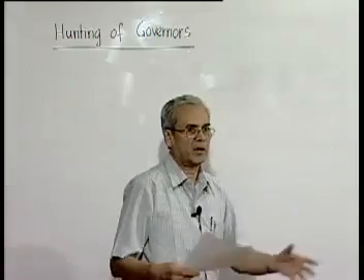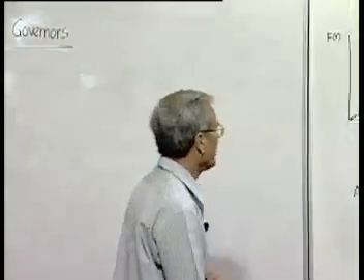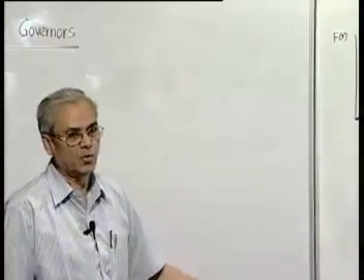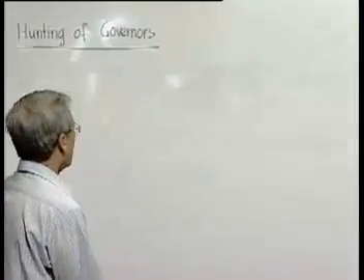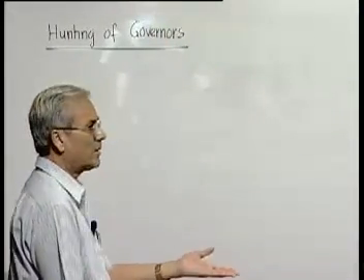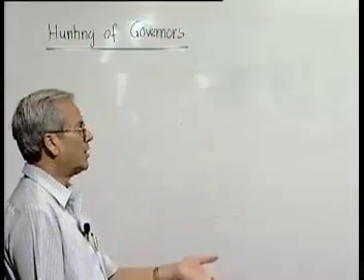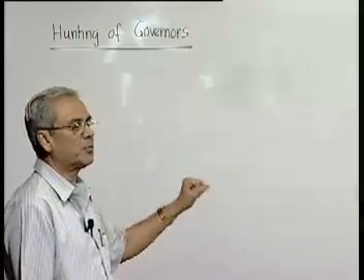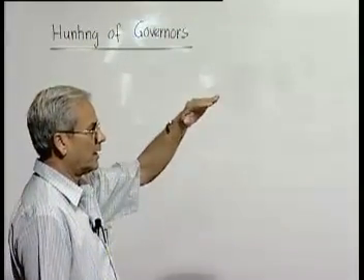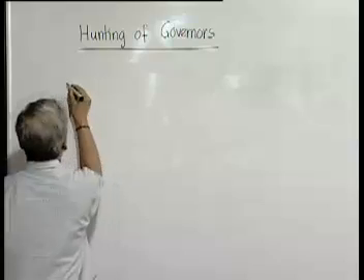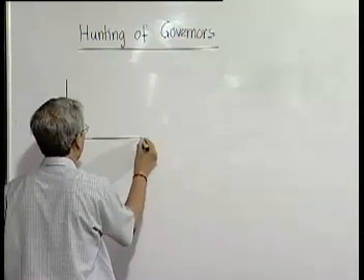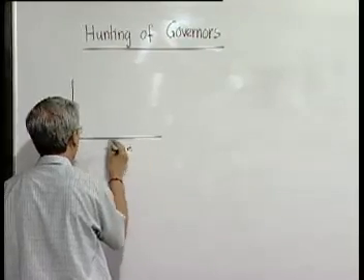Now, we have seen how a governor functions when a system is running. Suddenly, due to some reason, maybe a change in the load or change in the input, whatever it may be, suddenly maybe the load is less. So the governor will try to speed up, and as it speeds up, we are controlling, cutting down its input. Therefore, it will again start coming down to the required level of speed. But due to the finite inertia of the whole system or mechanism, it does not stop when it reaches the required speed. That means graphically we can explain that if we plot the speed with time.